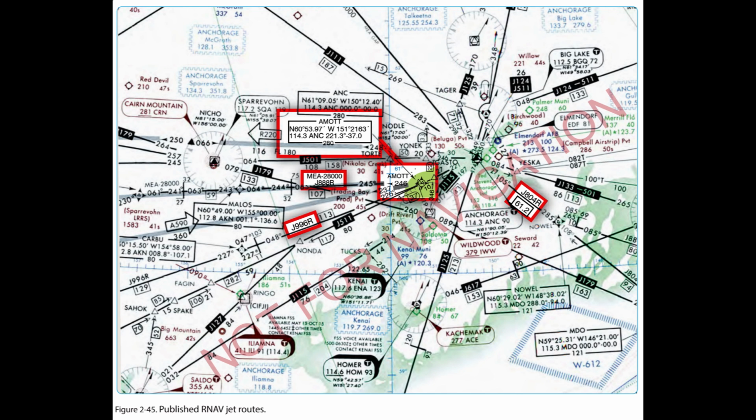Note, to be approved for use in the NAS, RNAV equipment must meet the appropriate system availability, accuracy, and airworthiness standards. For additional guidance on equipment requirements, see Advisory Circular AC 20-138C, Airworthiness Approval of Positioning and Navigation Systems. For Airborne Navigation Database, see AC 90-105, Approval Guidance for RNP Operations and Barometric Vertical Navigation in the U.S. National Airspace System.